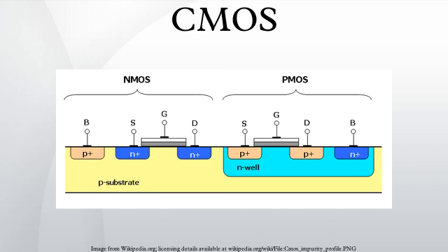An advantage of CMOS over NMOS is that both low to high and high to low output transitions are fast, since the pull-up transistors have low resistance when switched on, unlike the load resistors in NMOS logic. In addition, the output signal swings the full voltage between the low and high rails. This strong, more nearly symmetric response also makes CMOS more resistant to noise. See logical effort for a method of calculating delay in a CMOS circuit.